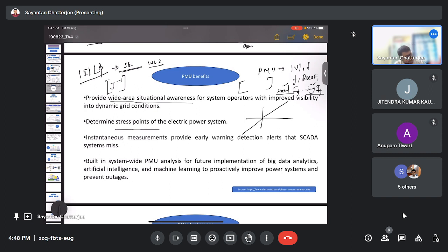What we can observe is that it comes down with this kind of shape. But if we consider the real and imaginary parts, the Jacobian section remains positive throughout, and hence the inversion process is easier and the state estimation can be directly implemented. That's the reason for using the real and imaginary parts of the current, from where we can directly reconstruct the magnitude and angle again.